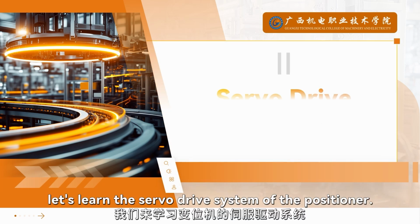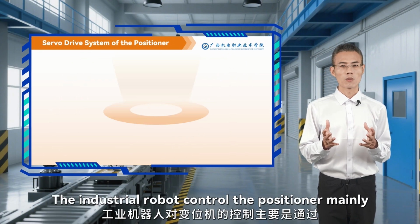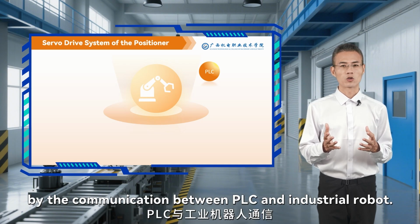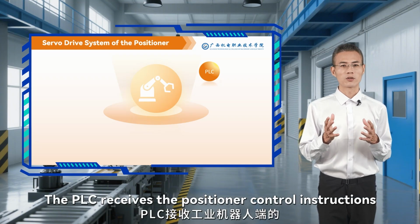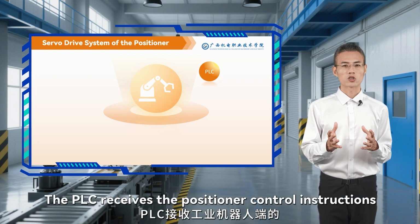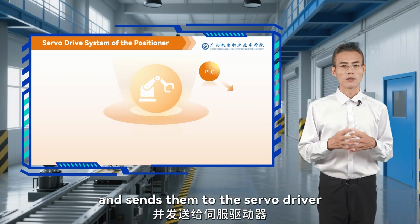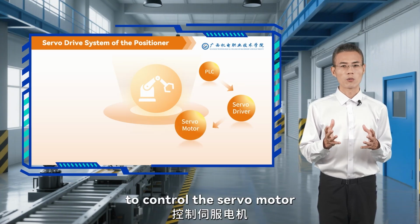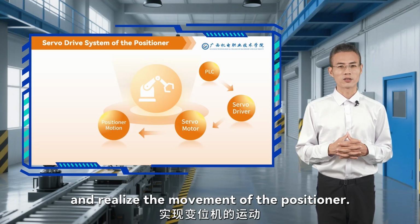Next, let's learn the servo drive system of the positioner. The industrial robot controls the positioner mainly by the communication between PLC and the industrial robot. The PLC receives the positioner control instructions from the industrial robot and sends them to the servo driver to control the servo motor and realize the movement of the positioner.